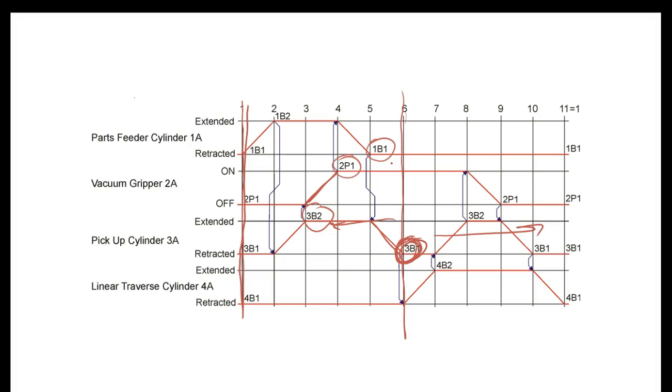When we use the term actuator, we mean it's either a linear actuator or a rotary actuator. Usually when we use the term rotary actuator, it's something that's less than 360 degrees. And over 360 degrees, we usually say motor. So yeah, that's exactly what's happening. But odds are if 3B2 is defective, if it's on all the time, then this guy right here is depending on 3B2. So your vacuum would come on instantly. It would stay on, yeah, if it was messed up.